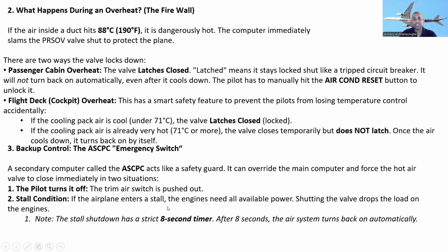If the airplane enters a stall, the engines need all available power. Shutting down the valve drops the load on the engines. Note, the stall shutdown has a strict 8-second timer. After 8 seconds, the air system turns back on automatically.